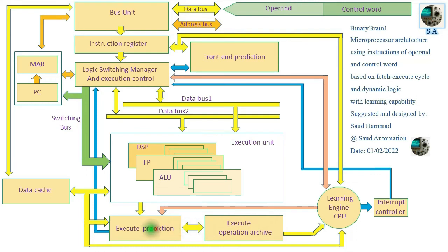Based on this, it will just execute the same result directly without needing to process that instruction through. Then it discards the currently fetched instruction and allows the program counter to increment to load and fetch a new instruction immediately.